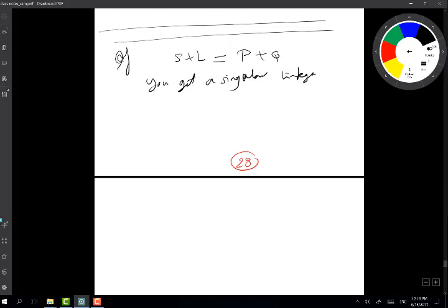linkage. For example, if I have this case here, right? So this is equal and parallel. At some point in time, you'll find that this point A will fall here, A prime, and point B will fall here, B prime. So the whole linkage collapses to a straight line.